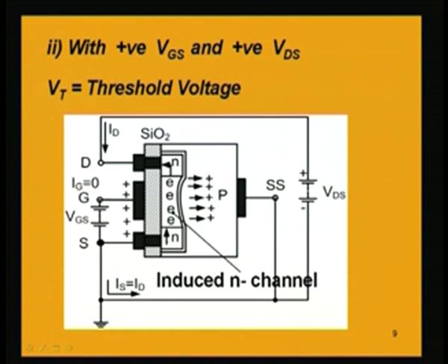If you recall, in a P type of semiconductor, the holes are the majority carriers, and here we are pushing away the holes. As they are being pushed away, they will be uncovering the immobile charges, which are nothing but the acceptor ions, which are negative ions.